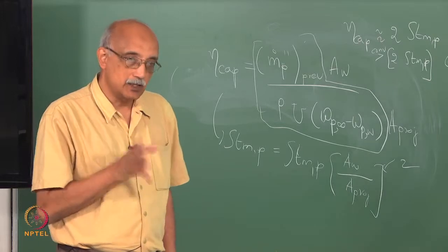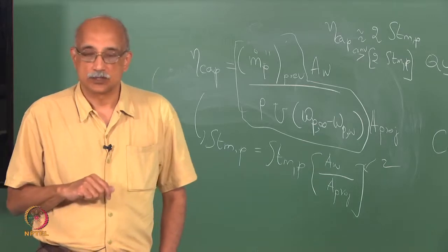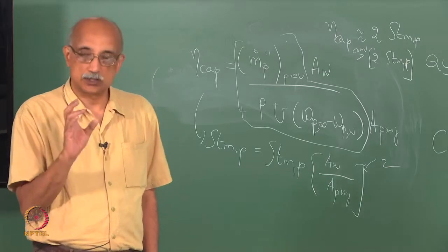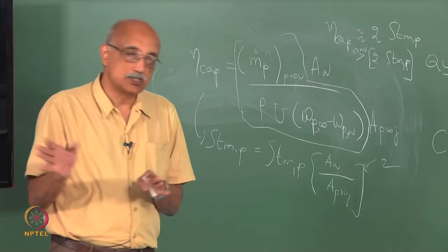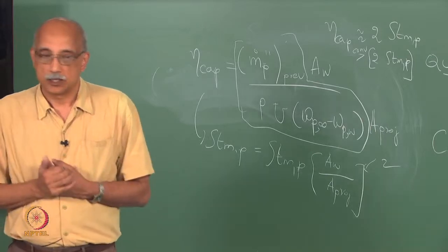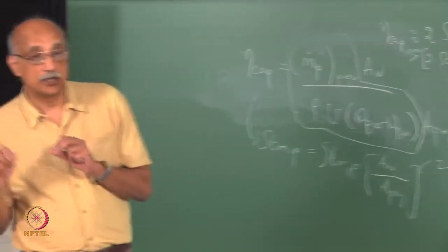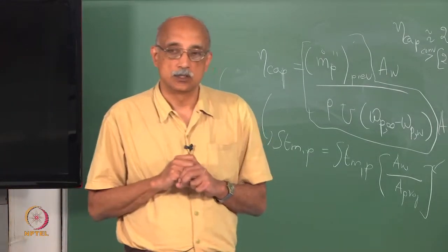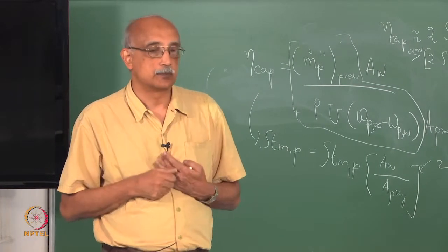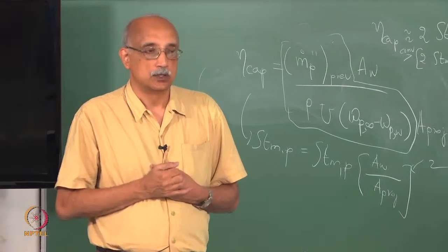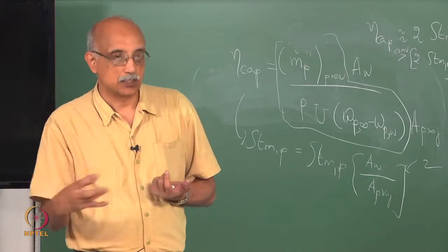We also said that in many cases you would want to maximize cohesive strength, but minimize adhesive strength. And so, there are some very subtle considerations that play into how you do that. And the other place where cohesion comes into play is flow. In particular, the flowability of suspensions depends very much on the degree of cohesivity that is present in the suspension. The more cohesive the particles are, the more the system will behave as a 2-phase flow. You will have one continuous phase of the carrier fluid and a second continuous phase consisting of particles.